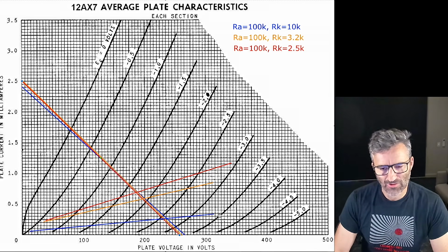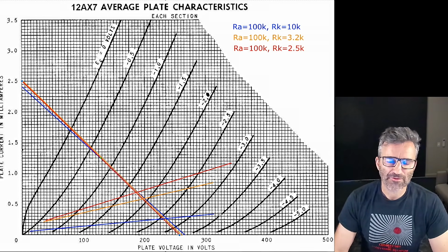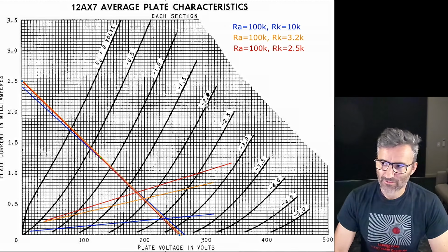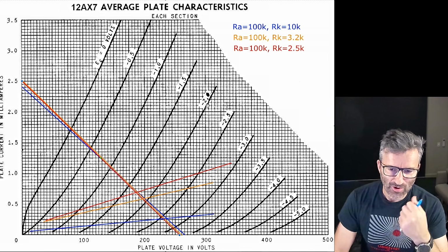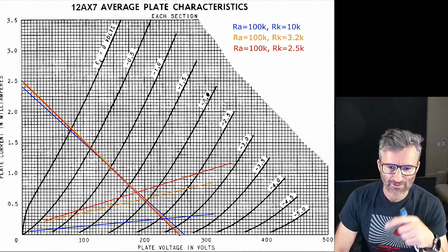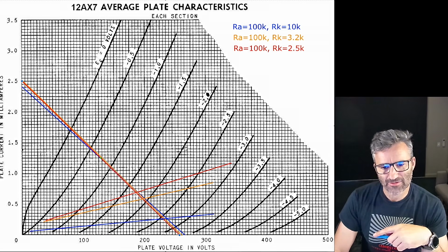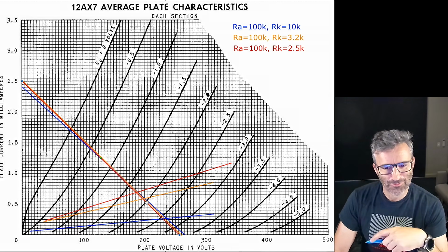Okay, so remember the triode, we've got the plate, we've got the cathode, the grid voltage coming in. Now we have to bias the grid voltage with respect to the cathode, and as I said earlier in the clip, if our cathode voltage was 2 volts, then the grid voltage is effectively minus 2 relative to the cathode. So this tells you that on this line here, where this line intersects with the load line, is your bias point if your cathode voltage was at 2 volts, right?